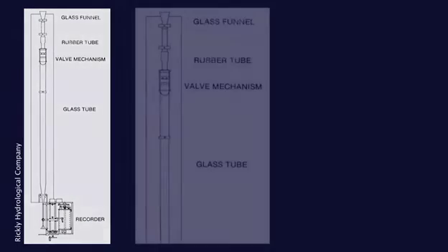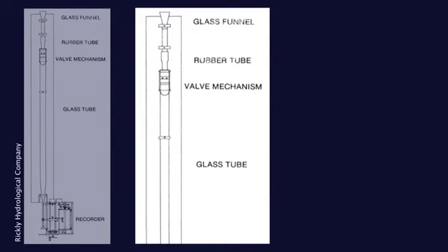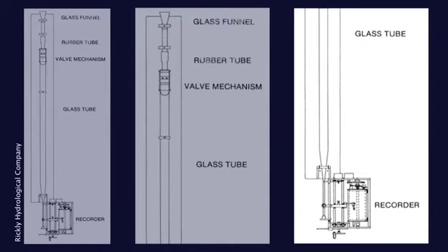The visual accumulation tube, or VA tube, is a fast, economical, and accurate method of determining the size distribution of sediment samples. In the VA tube method, the particles start falling from a common source and become stratified according to their relative settling velocities. At a given instant, the particles coming to rest at the bottom of the tube are of a certain sedimentation size, finer than particles that have already settled and coarser than those still remaining in suspension.